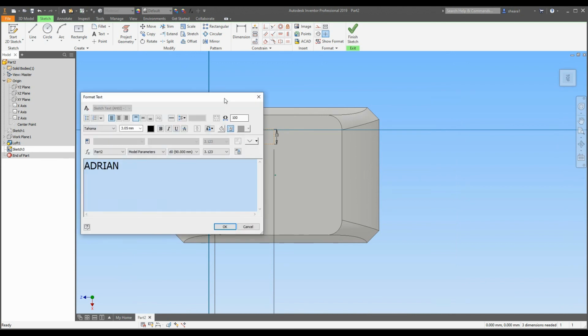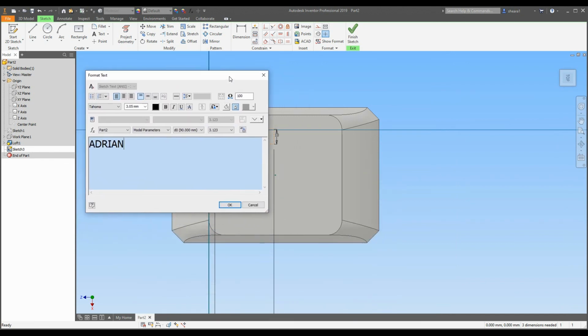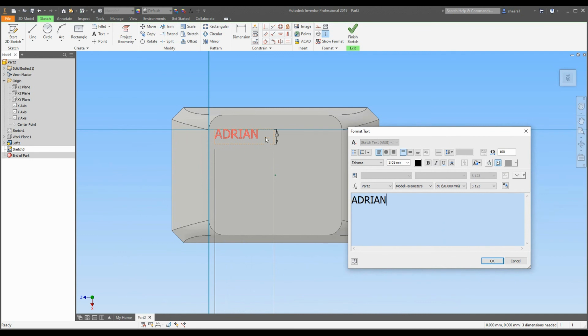I'm going to double click on the text again, and let's say we want to center the text on this box. So if I know the numbers of all these edges already, I can just apply some dimensions, going from the sides of this box, say like the top of the text box to the top of our shape here.